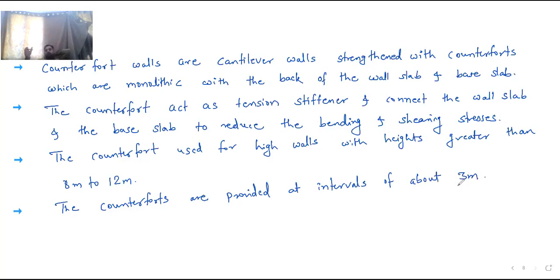So after every 3 meter, the counterforts are provided. It will also give support to the wall slab, and it will also connect the wall slab to the base slab, so that there will be a reduction in the bending and shear stresses.